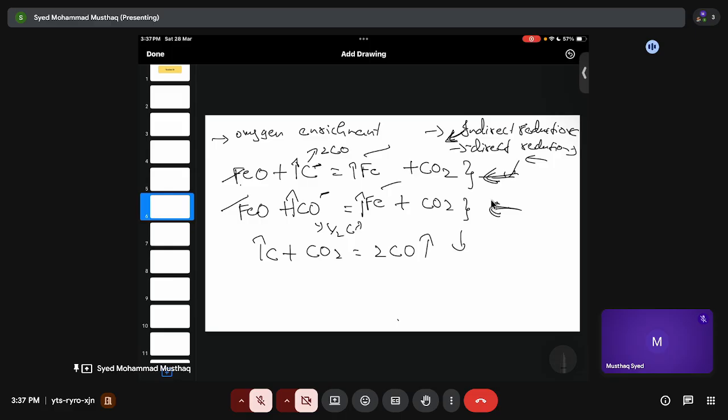Again, an increase in the top pressure of the blast furnace gas reduces the pressure difference between the gas at the stack and the tuyere level, which again decreases the ascending energy. So what do I mean? For example, if you follow Bernoulli's equation, P1 plus half rho V squared plus, I guess, rho g h, or P by rho g. Okay, let's check this out. Let's write everything in mass.